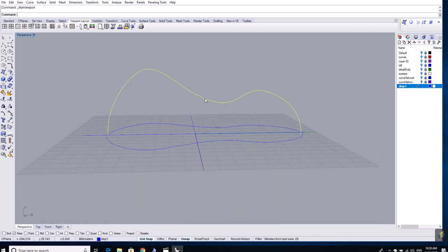So if I want to edit this line before we make the cross sections, it's really simple. I just have to turn on control points. Okay, so Window F10, turn on the control points, grab a control point and edit, and it allows you to sort of fine tune the geometry you're making. And again, I'm just sort of running through this. I'm not really designing anything nice. I'm just sort of playing around with it so that you learn the techniques.